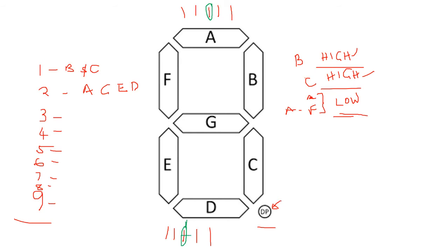Therefore, if we have taken out the major pins, the ones in the middle, which pins are left? We are left with 1, 2, 3, 4. So this pin 1 is responsible for the decimal point. Even if you try live, connect this to a positive power through a resistor, and then take another jumper wire from 5 volts, or probably you can ground that, take it from ground, and when you touch this with the wire, you'll see which LED lights. So once I've connected this to the ground or the positive or 5 volts, and then I touch this pin, it will light.